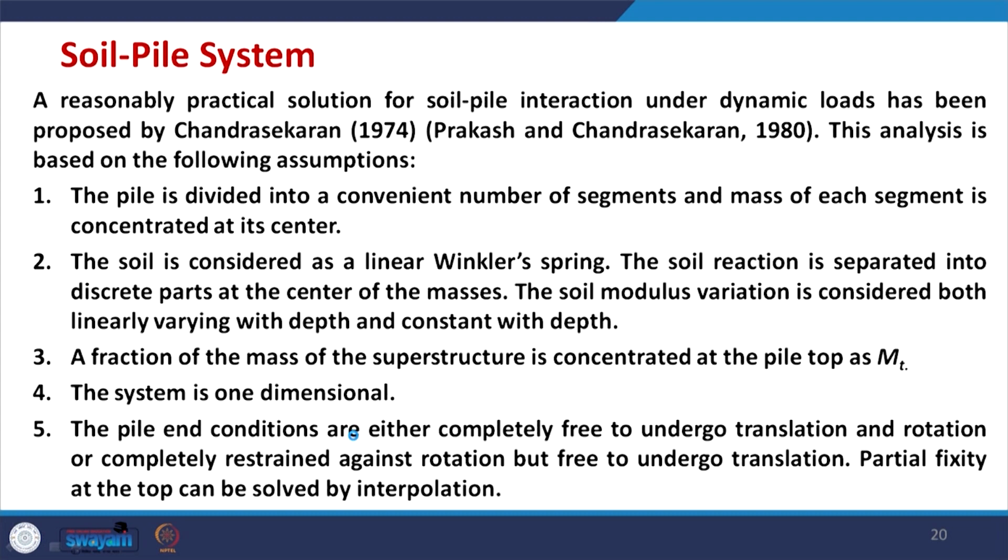The system considered is one dimensional. The pile end conditions are either completely free to undergo translation and rotation, or completely restrained against rotation but free to undergo translation. Partial fixation at the pile top can be solved by interpolation.